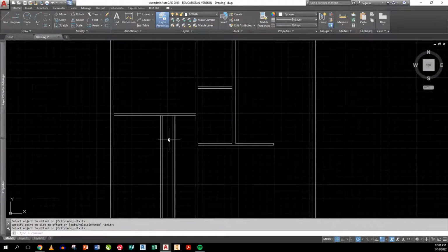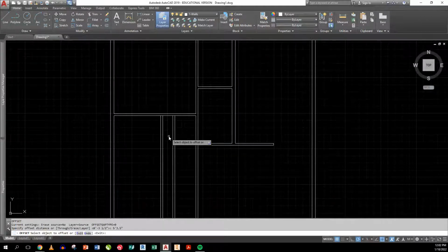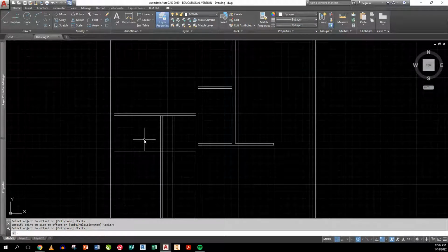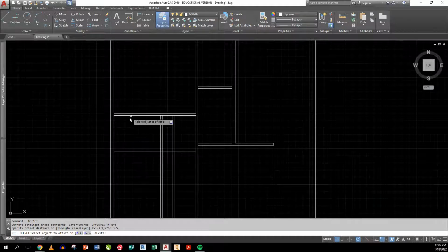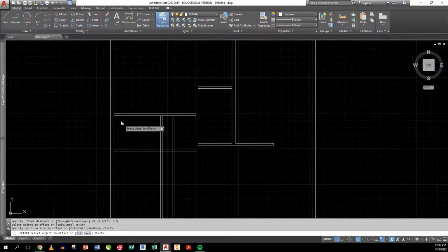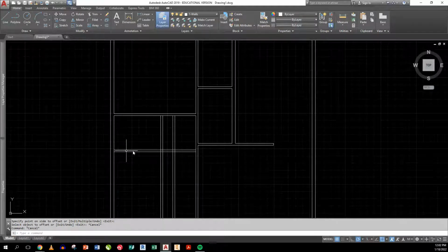Okay. Now the only things I have left to do is to do some trimming here. So I got to offset a little bit first. I need to put in the sides of this walk-in closet. It's 5 foot, 3.5 inches. I'm just going to click on here and go downward and then enter twice. Do 3.5 again, and the dimension this time comes back in. The dimension on this closet that I had went from here to here. Okay, if you look at the plans.